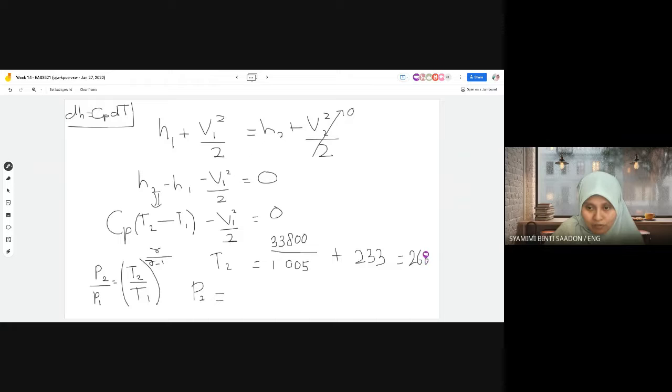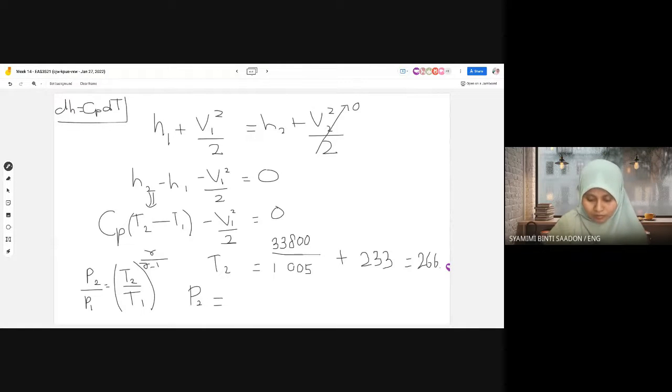Any questions so far for the diffuser? This method we use a lot in propulsion next semester. We introduce it first in aerothermo, and you continue for the actual case, two-stage, two-spool turbofan, all in propulsion. So you get T2, P2. I'm rushing, so I didn't develop it in detail, but I guide you. You use this isentropic ideal gas relation, you get P2.